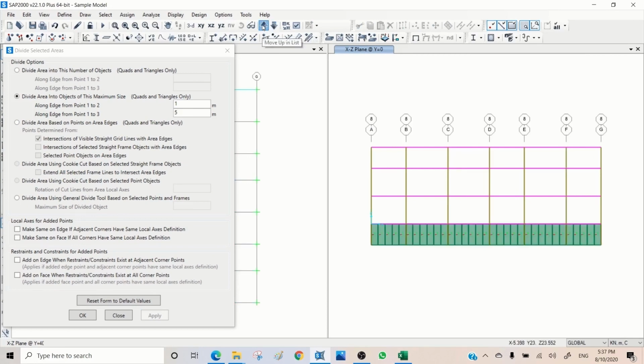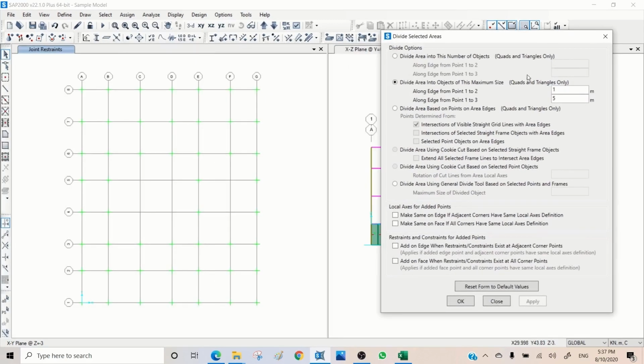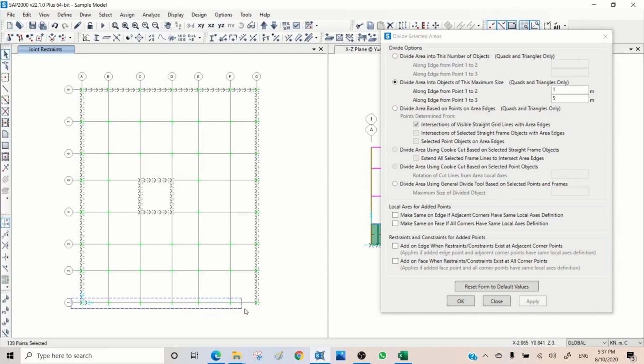Yes. Now I have a better connection with ground. So what I'm coming here, I need to select all joints here. That is including all joints here. So you can exclude the joints of columns if you want, or you can add them all together. Because columns are confined at the basement, you don't have too much moment, but it's really up to you. You can come here and again by clicking on columns one by one you can deselect them. So every click is select, the next click is deselect, so that's automatic. You don't need to choose deselect option.